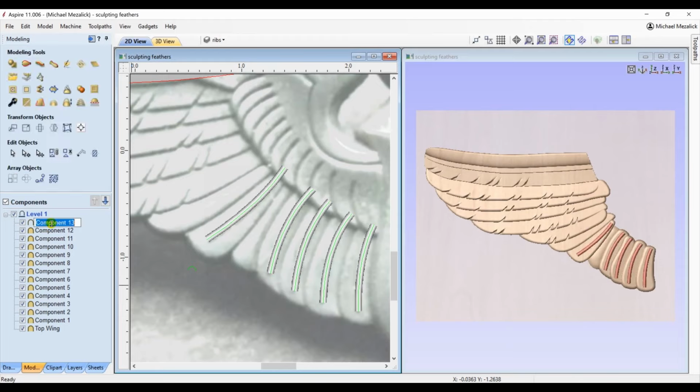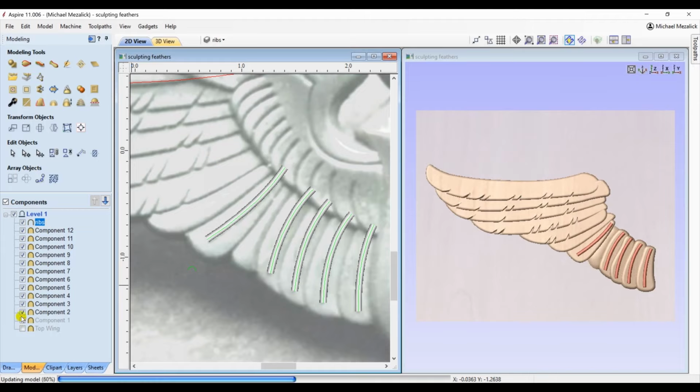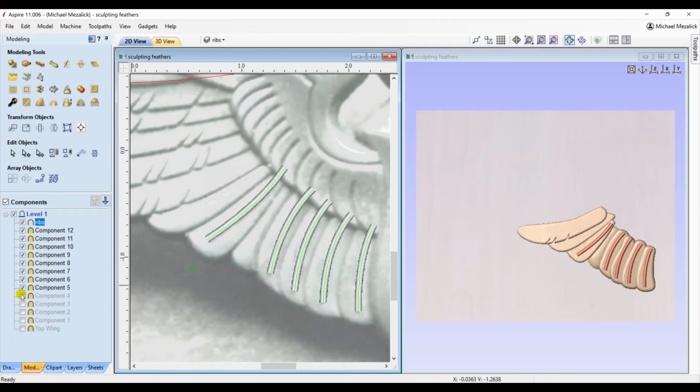Next up is another process that I use on a regular basis. Once I'm happy with one section or a few things that are together, I will take those and make a copy of the visible model. So I'm only working with that group that's been made into a model or a component itself. I reduce the risk of me moving things out of place because I've spent the time arranging them correctly, and I don't want to ruin that.